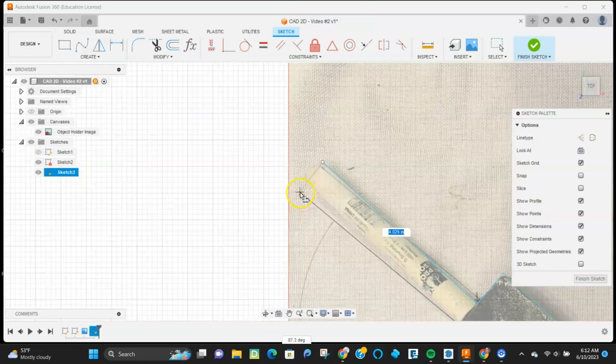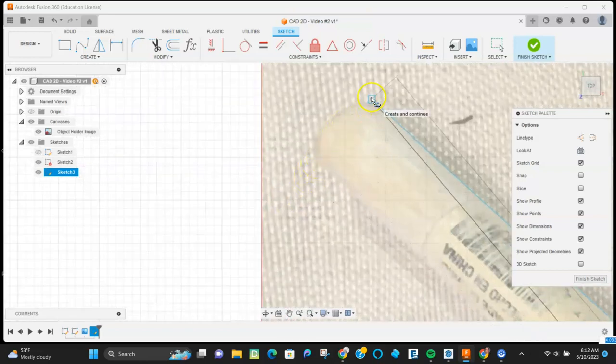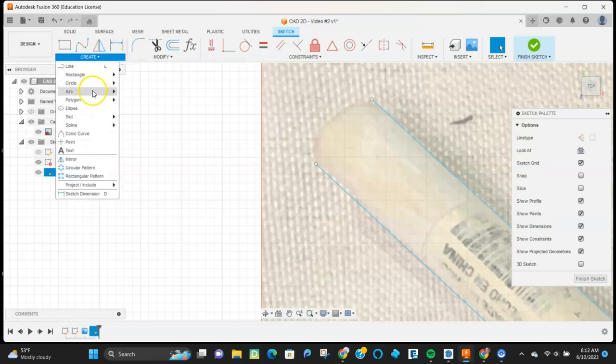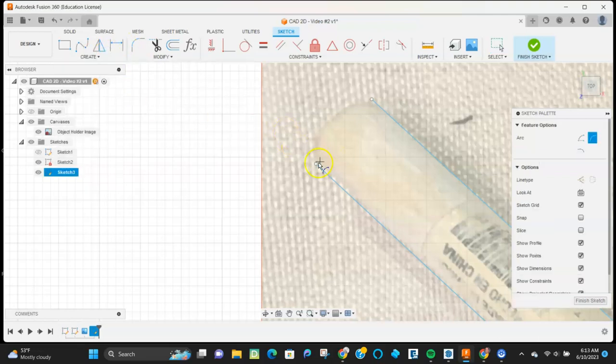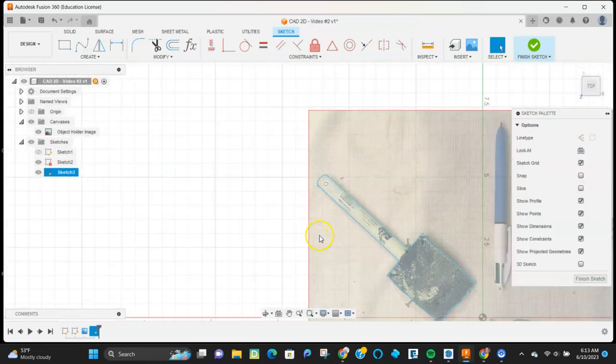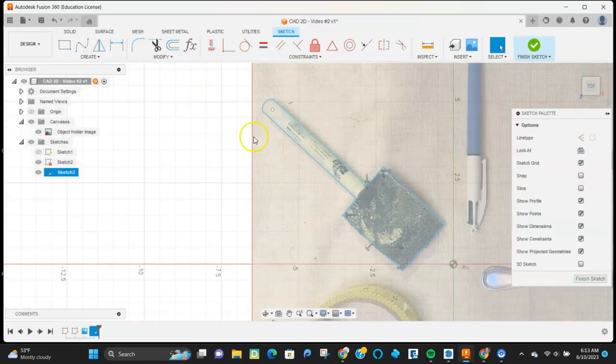And then I'm going to go back up, and I want it to be across from that one. So I'm going to hover over that and bring it across and see if I can find where that point is. And now I want to use an arc between those so that I can actually adjust that value. So I'm going to hit escape, go over to the arc, a 3-point arc. There's 1 point, there's another, and then I'm going to pull it up to be about there. And it is shaded that shape, and it's a closed shape around that paintbrush.